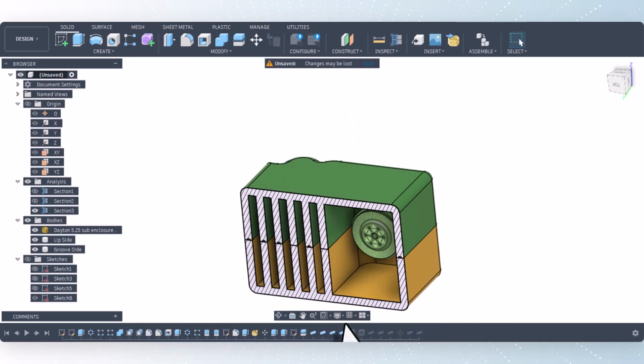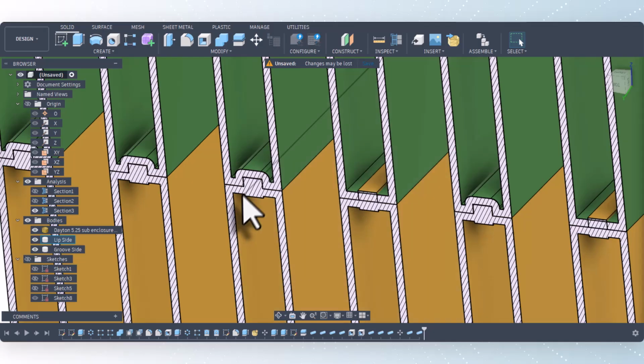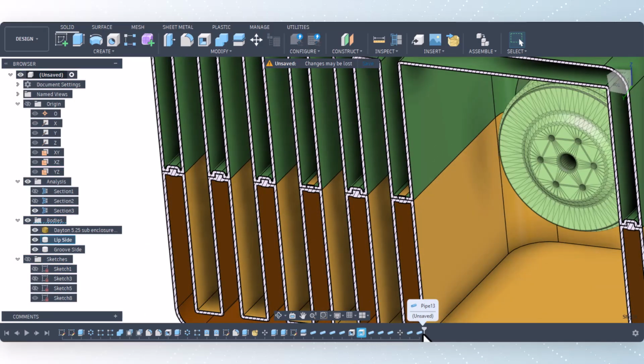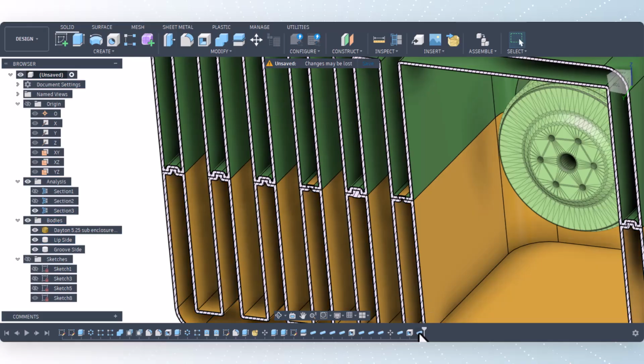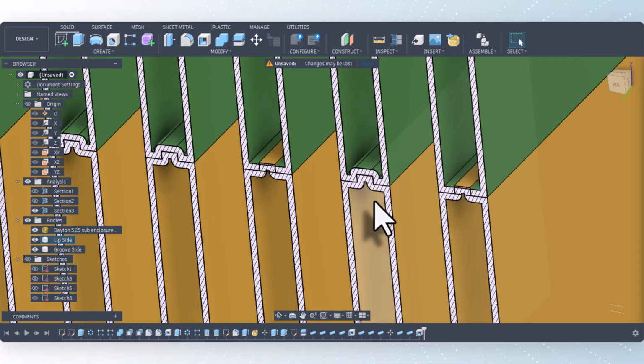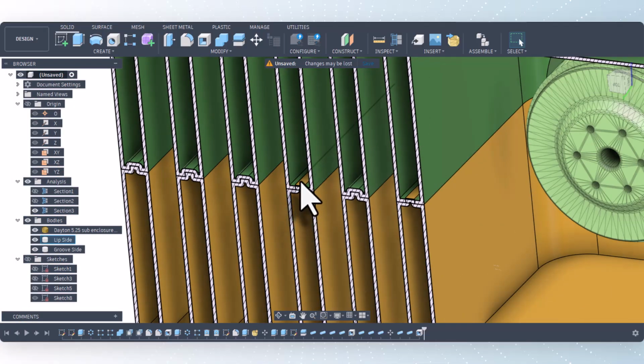There was one thing that I wanted to just show in addition on the shell. If I don't want this little protrusion down here, I could do this shell after the lip. So move that down. Let me move this one. Okay, but see, then it leaves this. So I wasn't sure whether you would want it like that or the way I had it before. So the only thing that needs to be done now is to add the groove here and here, and I think it'll follow that all the way around.